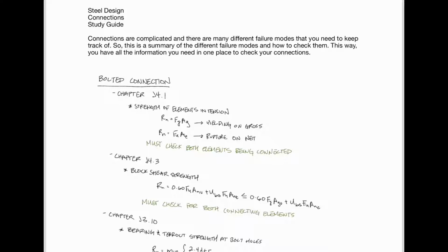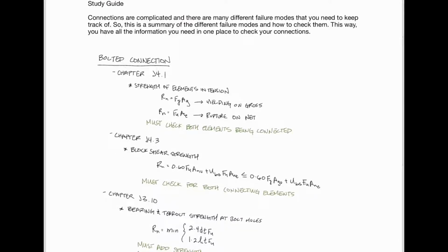Most of the firms that you'll be working for already have predetermined connections for you to use that have already been analyzed, so that you don't have to design a connection every time that you're designing a building, because again, it just takes way too much time and it's just not worth doing different connections for every element in a structure.